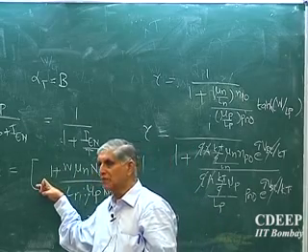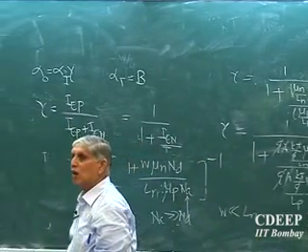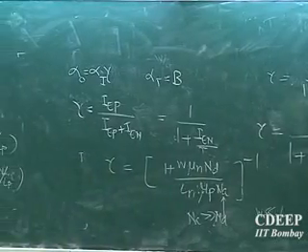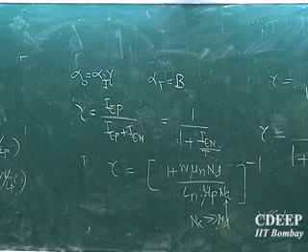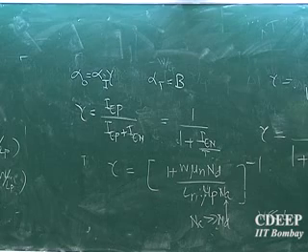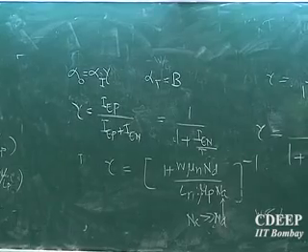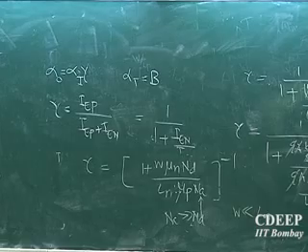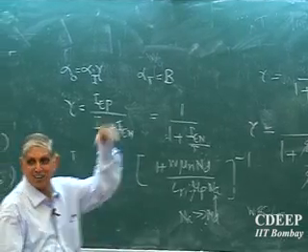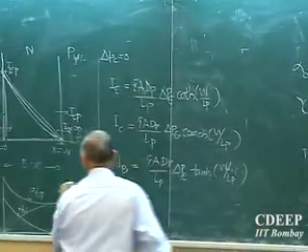Gamma tends to 1, and if gamma becomes 1 and alpha t is also made 1, alpha will come closer to 1, beta is alpha 0 by 1 minus alpha 0, so beta will increase, gain of a transistor will increase. So transistor design is: reduce base width, dope the emitter heavier. How much heavier, one person was asking today? Too much heavier also creates the opposite effect, some other day. It starts reducing gamma further. Okay, then see you tomorrow 11:30.